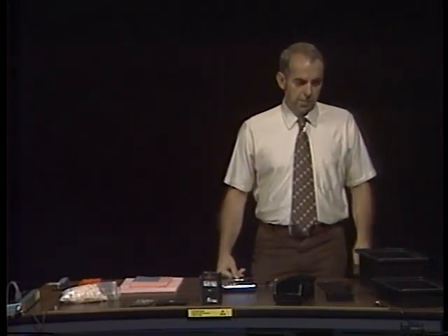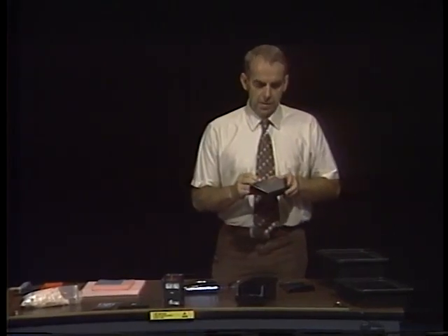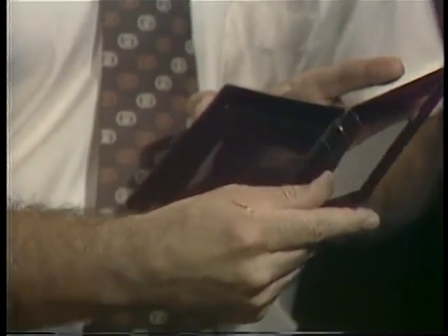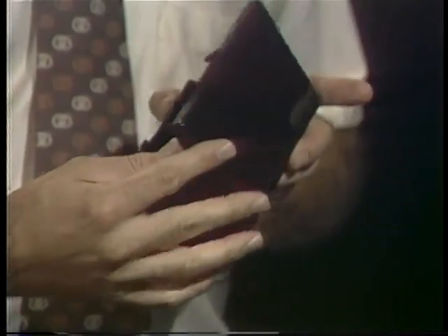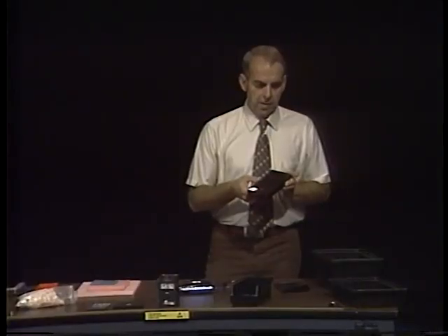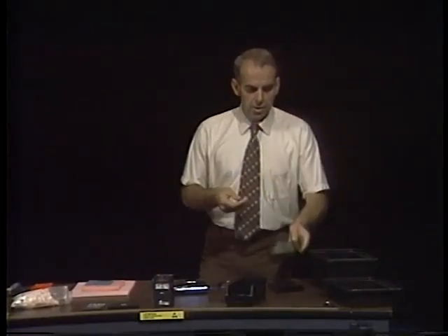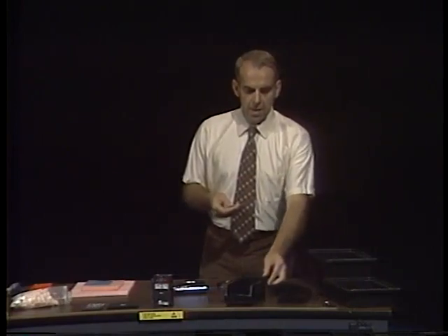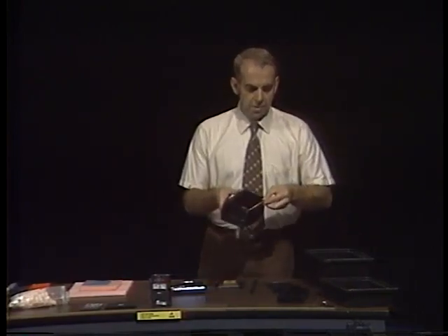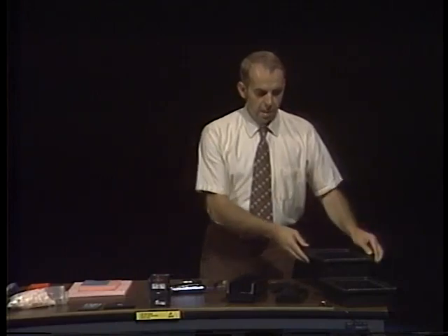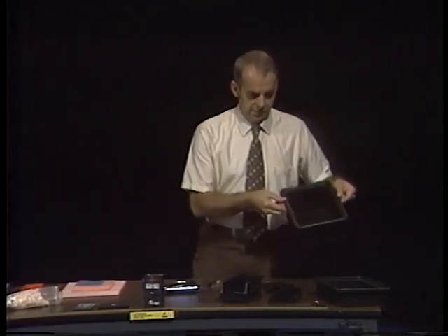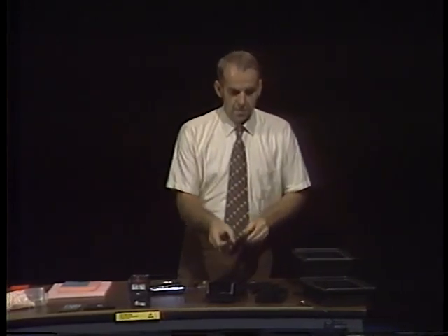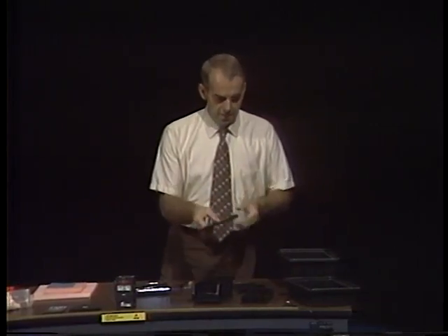Here are some examples of conductive containers, which, if they have lids, can be considered effective Faraday cages. This little carbon-loaded plastic box would be an excellent Faraday cage. In addition, conductive, anti-static parts bins are available, tote boxes, tubes for integrated circuits, and even plastic bags.